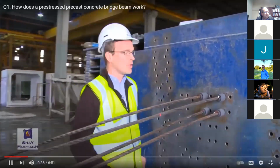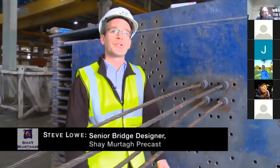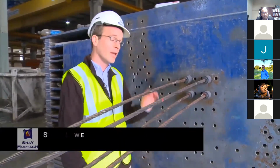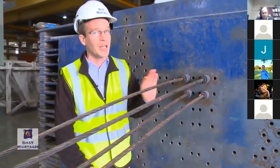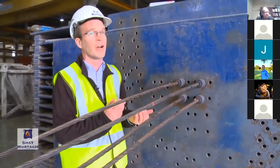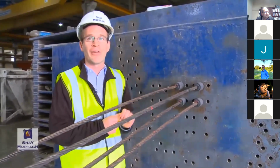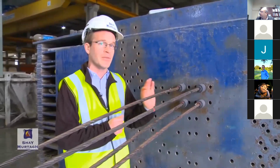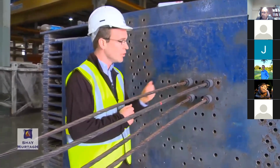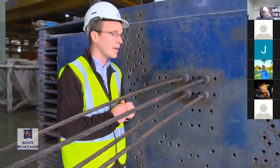Okay, now here is our typical stop end that would be used to orient the pre-stressing strands that we would use to apply that compressive force to the beam end. Now note, these strands are not in tension, they're slack, so there's no danger here. You must be very, very careful with fully tensioned pre-stressing strands because there's a massive amount of force that can be contained in each of these strands. This particular strand, in fact, we would actually tension up to a load of 209 kilonewtons in just one strand.